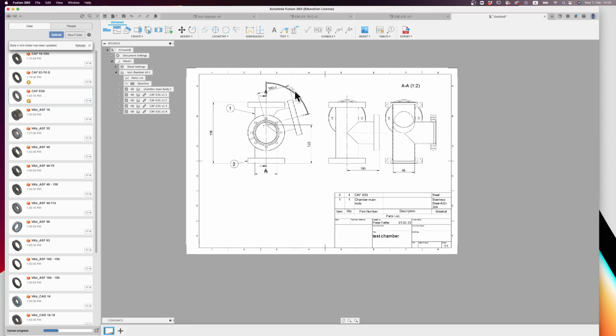0.1 degree is probably also a bit tight for a welding construction. But if you need it, then that's what you need. You just need to pay more for it. But you will see sometimes on the manufacturers they have certain price lists for certain tolerances that you can ask for. And the rest is then just moving stuff around so that things are not sitting on top of each other, so you can read them properly.